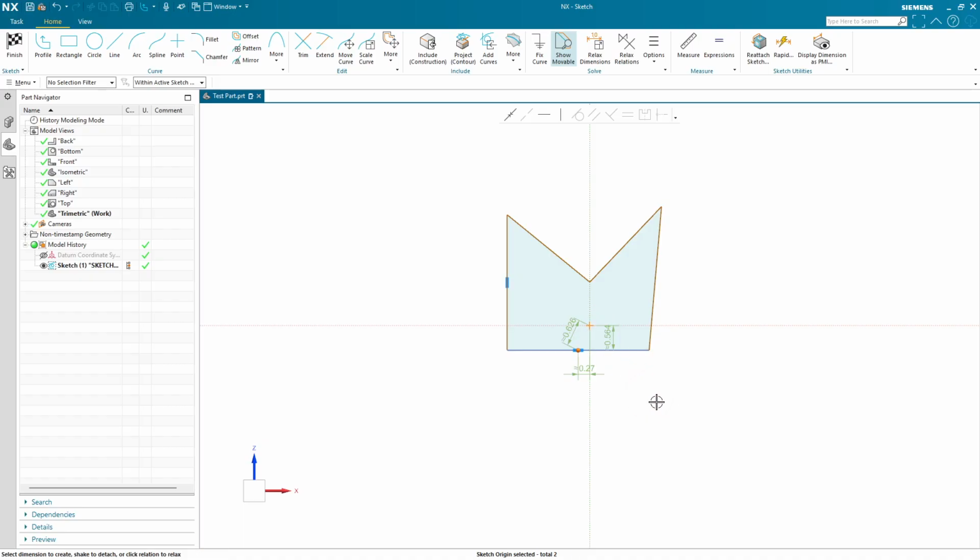From there, I'm going to pick that origin, and instead of messing with these dimensions yet, which we could possibly do, I'm going to pick these two things and just say, make these two coincident. And that will snap them and glue them together until I tell NX that they should no longer be coincident. So those two things are stuck on each other forevermore until I say otherwise.